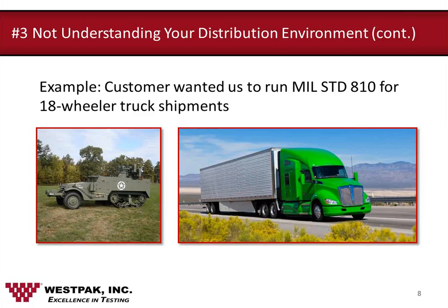So back to the question on LTL versus single parcel: does the FDA require that you validate both scenarios? I haven't seen our customers run through separate testing for LTL and single parcel. They'll usually just run it through one test, which is a worst case scenario for both. It's going to see vibration, drop, and compression in either environment.